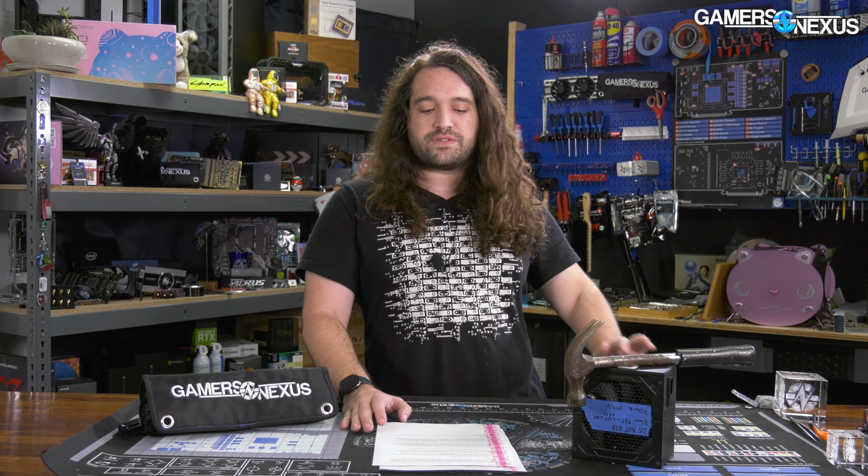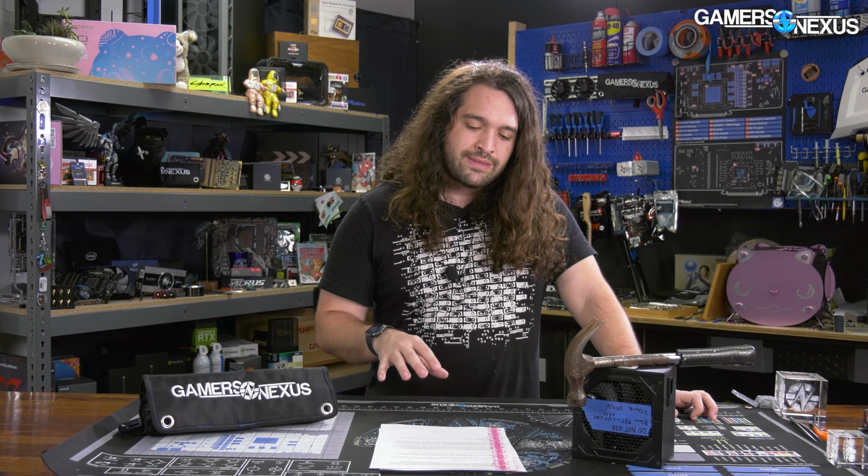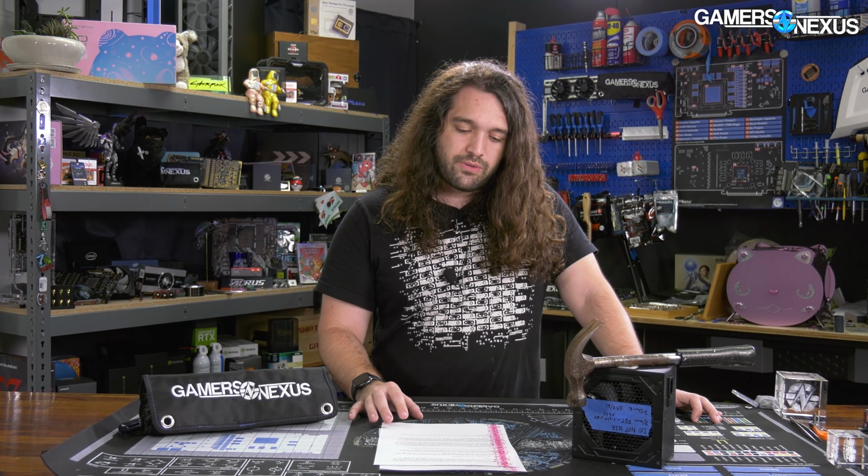The memory controller is really interesting. It's been a while since we've had right at the edge of a memory generational switchover. DDR4 and 3, obviously the last one. Now we're going 4 to 5. So the memory controller itself, which is within the CPU, it's been for a long time, it's the IMC, the integrated memory controller, that supports both DDR4 and DDR5. And so you're going to see solutions on the market that will support one or the other. You're going to need to be obviously aware of what platform you're choosing, what RAM you're choosing with it to make sure it all works together.